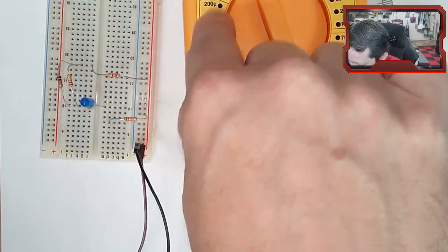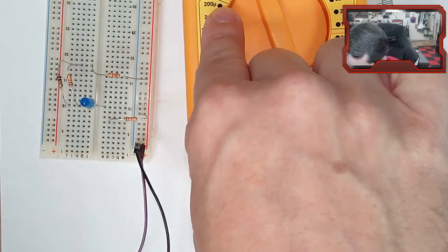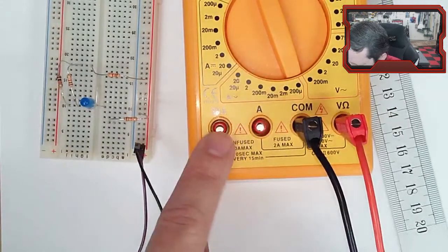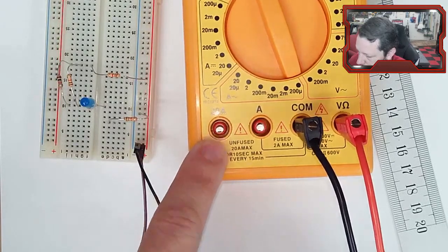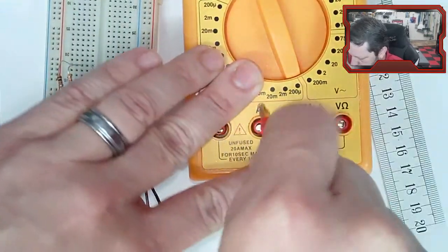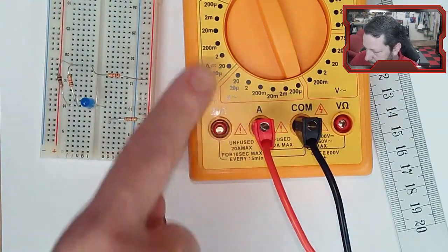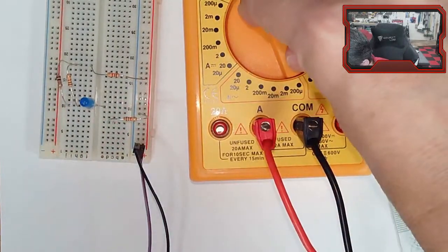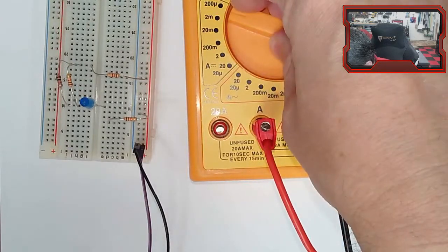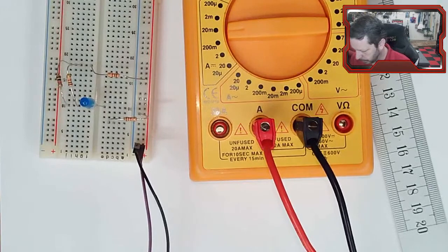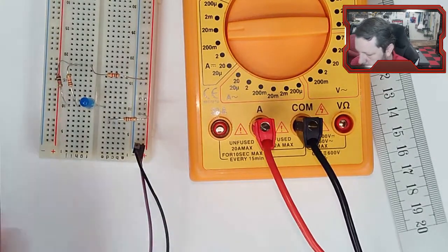And then we've got the same idea over here, where am I trying to measure 200 microamps, 2 amps, 20 amps? If I'm on the 20 amp one, I do have to switch over to this plug over here. Actually, I almost made the same mistake again. I do have to switch to this side to measure current. And let's go for the 20 milliamps. Let's see what we're at. All right, so to do that, notice nothing's actually happening yet.